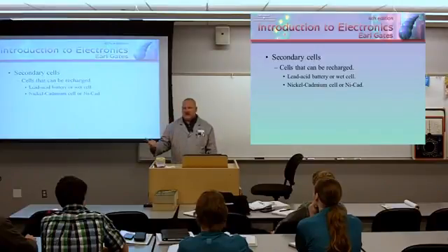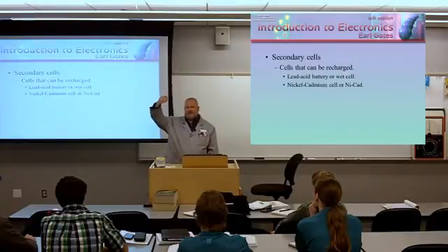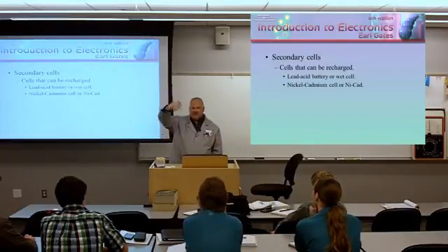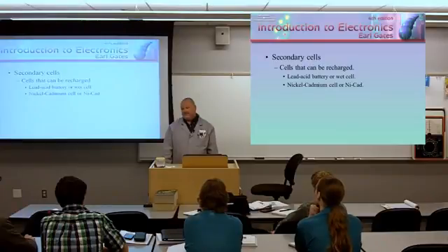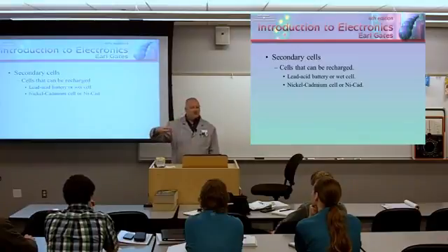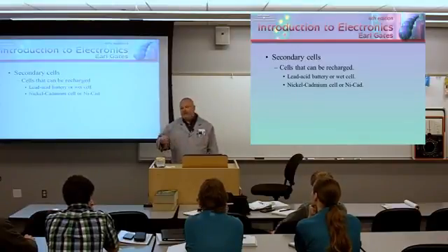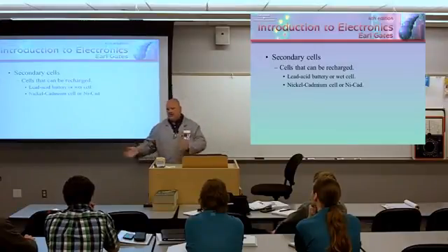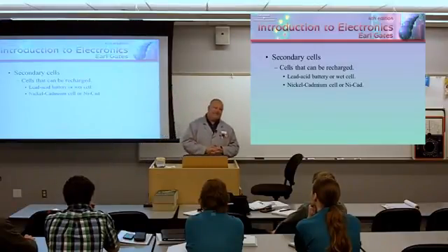If our nuclear reactor shut down or we had a problem, we could get to the surface. When we get to the surface, we could start up a diesel generator. So from that transit from the deep up to the surface, we needed to be on battery power. If you can't get the diesel started while you're on the surface, or actually at periscope depth, because we had a snorkel they could just stick up, where your induction systems for the diesel engine run the diesel, we had a generator connected where we could keep, not as much power as we'd have with nuclear power, but enough to keep all vital systems up and operational.